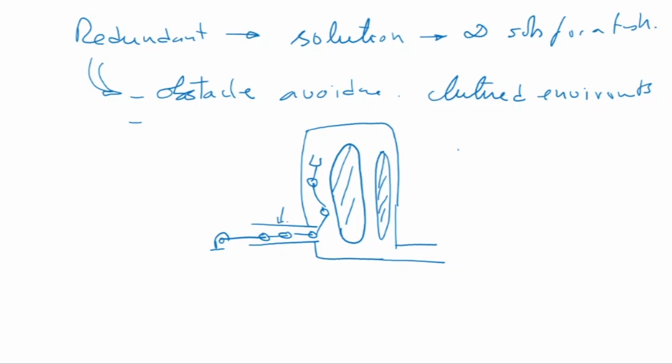It has multiple degrees of freedom, redundant degrees of freedom. Now when it goes into the pipe here, it loses the degrees of freedom, which basically means the manipulator cannot manipulate itself in the pipe. So it means that the degrees of freedom have been lost. But these degrees of freedom are there so that the robot can now go and perform different tasks. For example, it can go this side, this side, this side, get in there, do inspection, or catch something. Now this is a redundant system, because simply to move in free space you need only 6. But once you get constrained like this, where the degrees of freedom are being lost, then you have to add them to the total system.